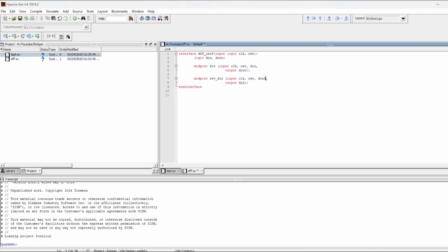So inside the port declaration of your DUT, you can just select a particular modport. And depending upon the modport you have selected, this particular direction will be assigned to its inputs. So the interface is not just providing the signals for the DUT, it is also providing a means of direction, and you can also restrict the direction for those signals to different modules.